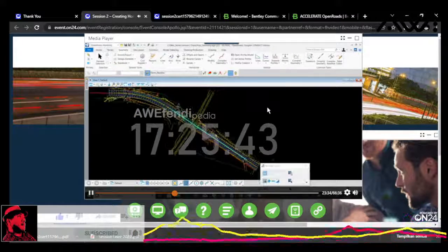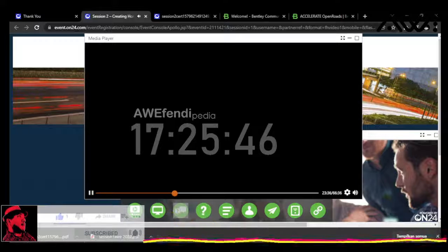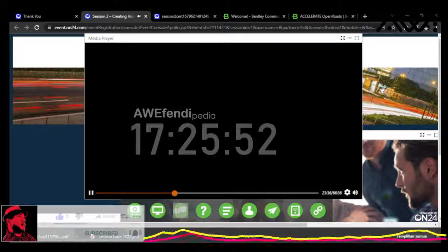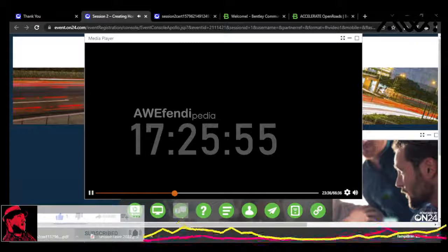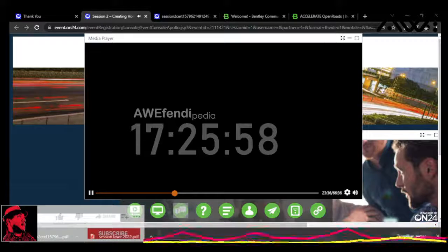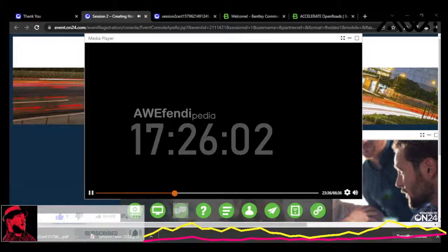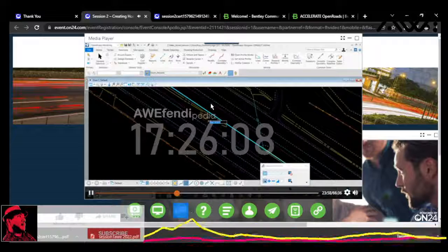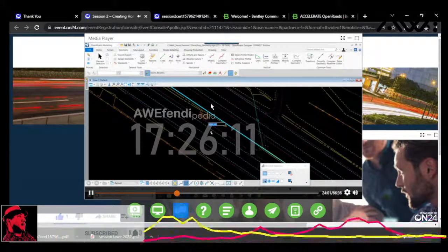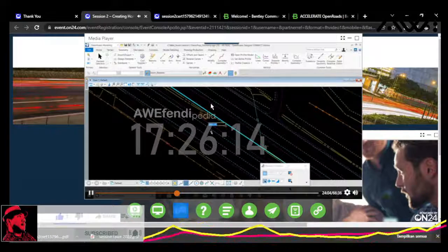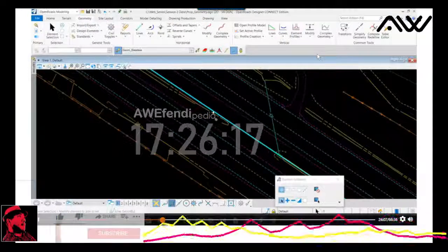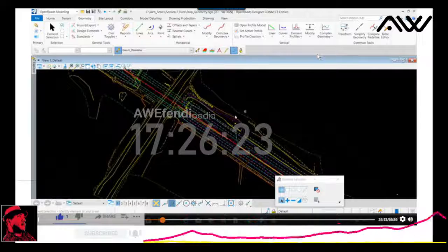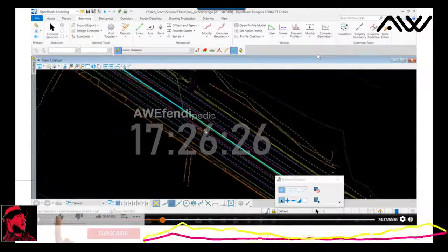Now, I will take a moment here because I want to point this out to you. As you're inputting data, as you're creating geometry, and as you're laying these elements out, it's okay if you happen to make a mistake. You key in the incorrect value for the bearing or the distance or whatever may happen. You can change that very quickly, meaning if you'll notice here, as you select that element, the dimensions, the bearing, the distance are active. I can click on either one of those dimensions directly and make a change. Okay? So it's really no more difficult than that. So again, just as an FYI, in terms of interacting with the data, click on those dimensions if you need to correct something.